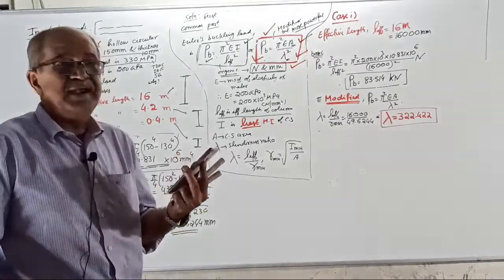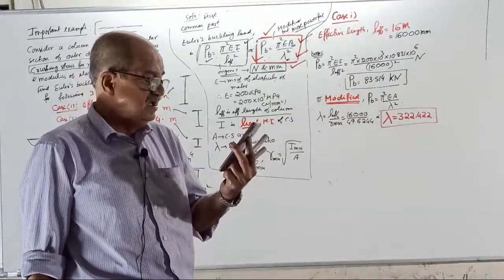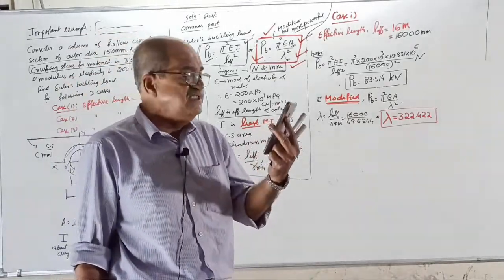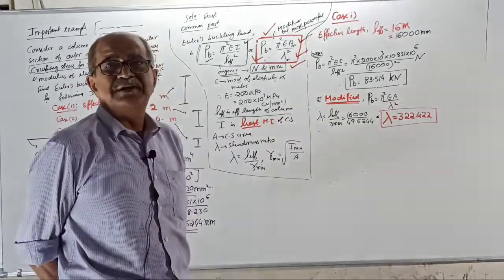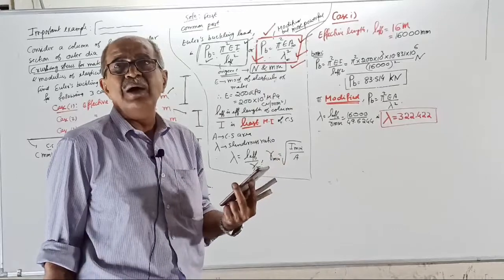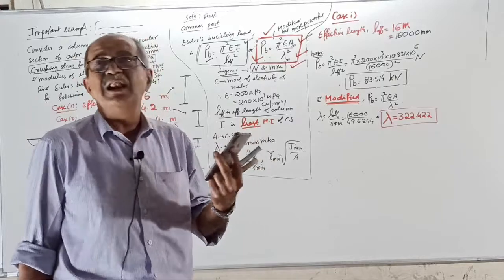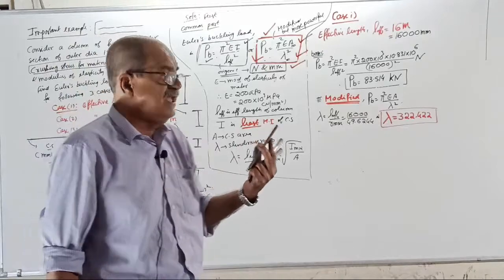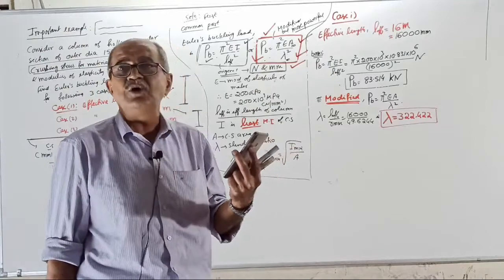Under normal cases for a steel column, lambda should not exceed the limit. Even if you say you will apply a much lesser load, they will still say nothing doing. That column looks dangerous just by looking at it. So tell me the answer: the upper limit for lambda at any cost under normal loading case, not the special case if you consider wind load or earthquake. It is not 80.